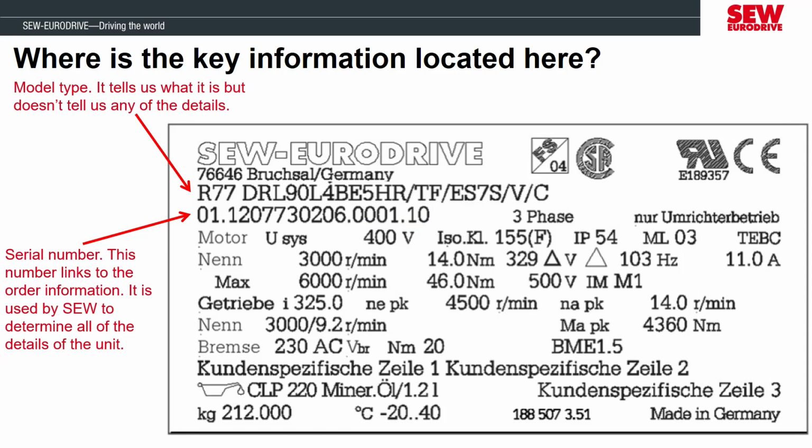Before we get too far from the top of the nameplate, I want to show you this logo above the model type that says FS04. This is a marker to indicate that the unit was assembled with some part that meets functional safety. This could be a mechanical brake, an encoder, or a combination of parts. If you see this marker and are needing to perform mechanical service to the motor, you will need to be careful because if you disassemble the unit, it could void the functional safety rating. Oftentimes, when a functional safety part is needed to be replaced, such as a brake, the unit will need to be sent to your local SEW assembly center to replace the part so the functional safety rating is maintained.